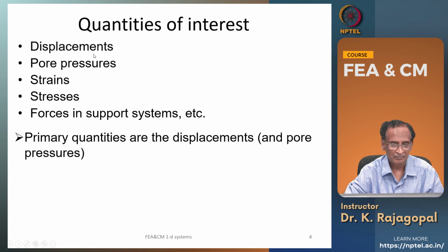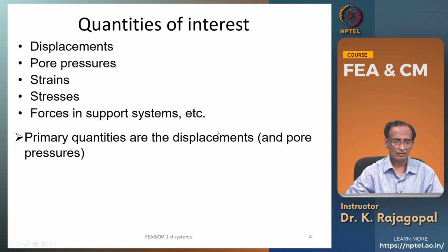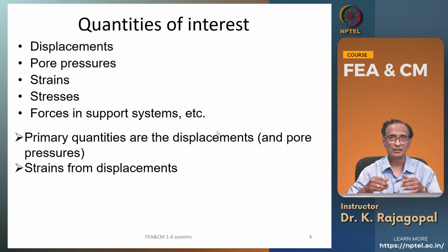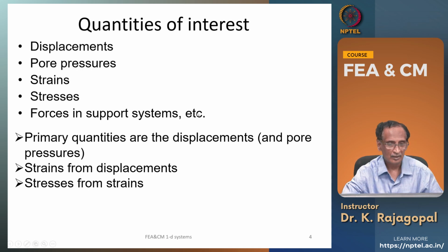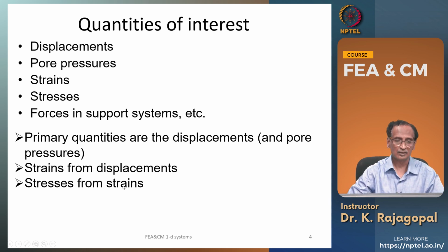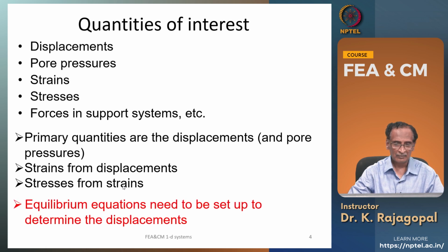Then in the problems with water, we also have the pore pressure, and we determine the strains from the displacements using the compatibility equations, and then we can determine the stresses from the strains using the constitutive equations that we will see later in some other lectures.